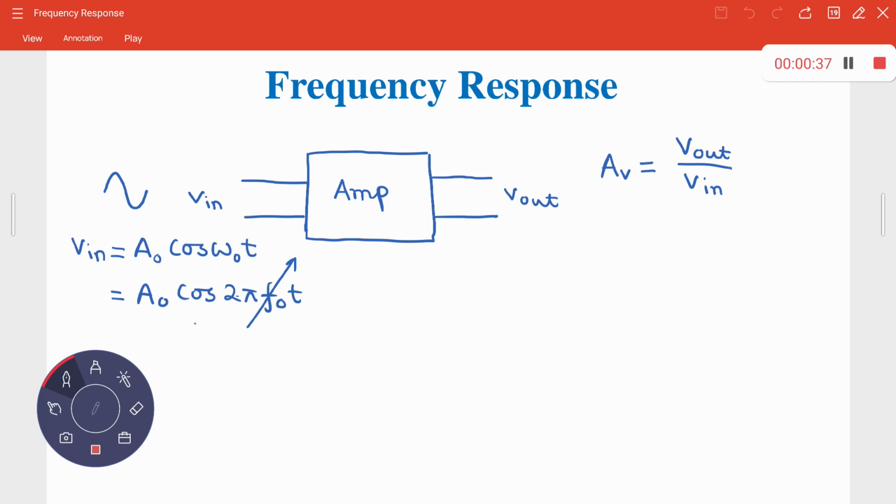types of topologies. Now, we have not considered the effect of any capacitors. Whenever you have studied the BJT based amplifier circuits, there also you have seen that there are a few capacitors which are externally connected, like the coupling capacitors and the bypass capacitors. And apart from that, you have different types of parasitic, internal capacitors, right? Here also you have different types of capacitors, and whenever you consider those capacitors, obviously the gain that you are getting is not independent of the frequency.